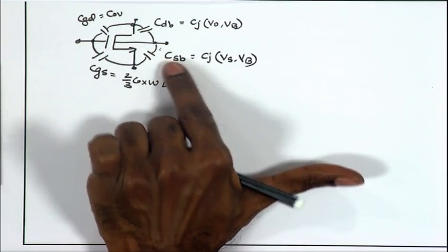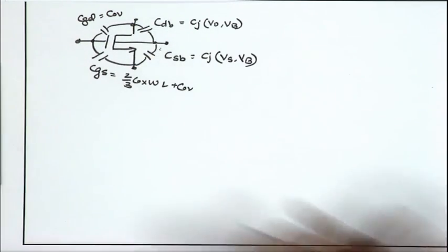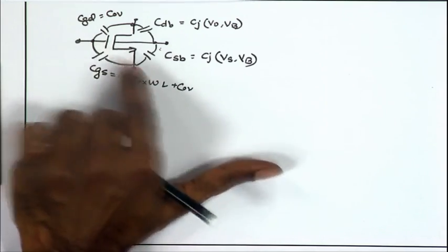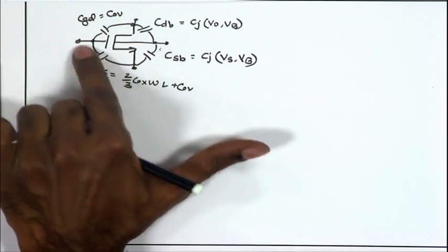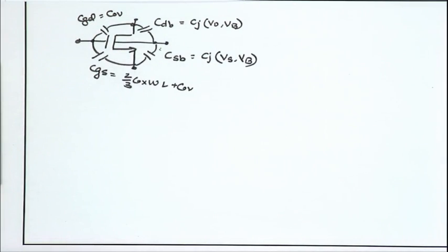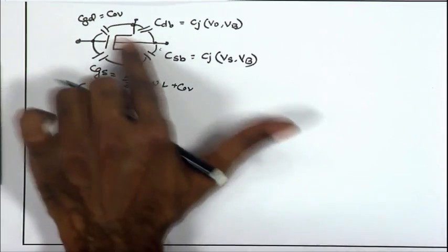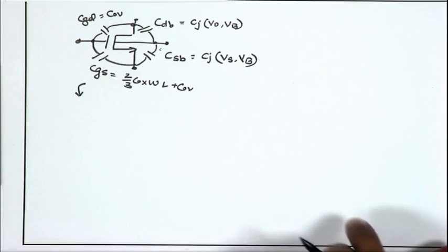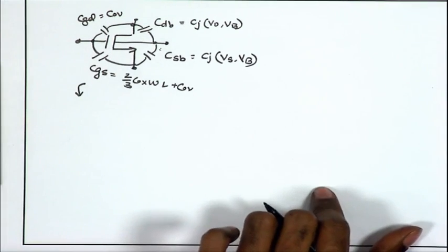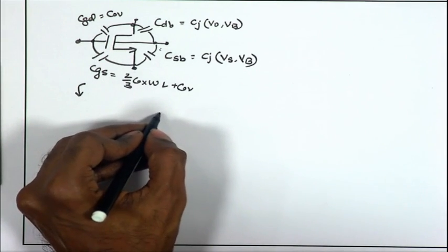So, both these junction capacitances are coming because of the reverse biased diode associated with the drain and junction, source and junction, and likewise we have the other capacitances between the gate and source, gate and drain, coming because of the channel charge modulation and the C overlap, and CGD comes only because of the C overlap. So, this basically completes our high frequency model. So, if I replace this MOSFET model with the corresponding small signal model that we have just seen.